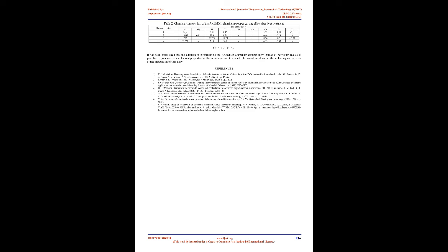Instead, a phase was formed containing almost 78% Si in the shape of rounded grains concentrated along the grain boundaries of the solution. Zirconium is presented in the form of a triple compound with silicon and aluminum, which also concentrates in the form of plates along the grain boundaries. The change in the shape and size of the phases containing silicon and zirconium makes it possible to increase the strength of the alloy to 363 MPa after heat treatment. The structure of the heat-treated alloy is shown in Figure 4.